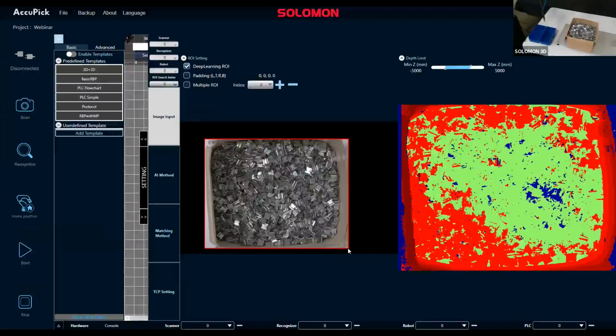And this is actually kind of important because in the real case on the production line, sometimes the clips can actually fall outside of the bin, and sometimes there's a lot of clips just laying around on the floor. So we don't want to be recognizing those or trying to pick those. So we just set up different bounding boxes to make sure we only pick items inside the bin.